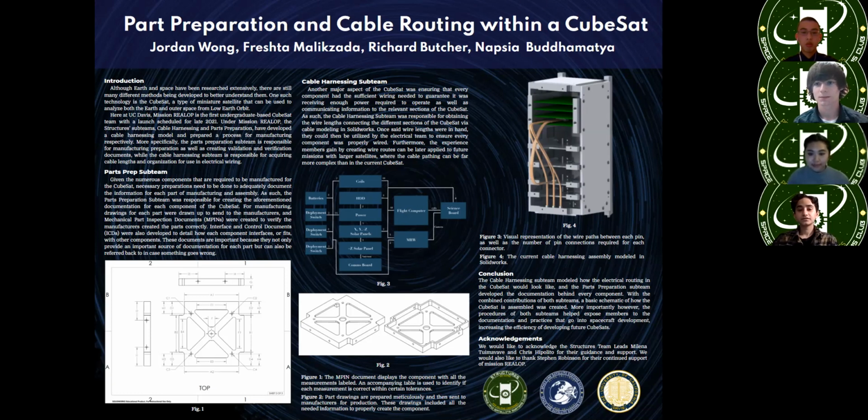So we used SolidWorks to route the wires by first modeling the connectors with the numbers of pins that were needed on the shelves. So there are connectors with different numbers of pins on each shelf, like 40-pin connectors or 2-pin connectors and so on. And then we had SolidWorks recognize those as connectors, and then we put the connectors inside the CubeSat in their specified shelves and made the needed routes between each connector. And then we adjusted the wires so there's no overlap between the wires inside the CubeSat. And then we obtained the wire lengths by flattening out the wires and getting their drawings.